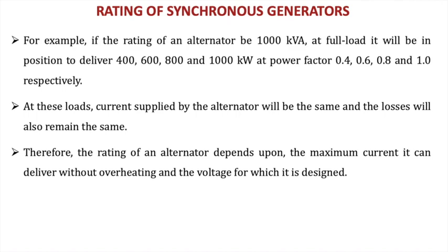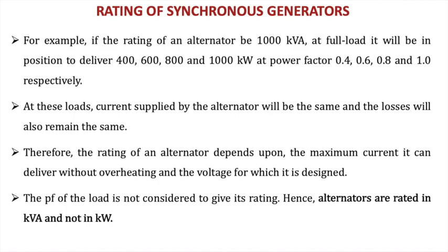Therefore, the rating of an alternator depends on the maximum current it can deliver without overheating, and the voltage for which it is designed. So the power factor of the load is not considered in giving the rating of the synchronous generators or alternators, and therefore they are rated in kVA and not in kilowatts. So this is the reason why these generators are rated in kVA. So what do you conclude? Because these generators are independent of the power factor, the generator rating is in kVA and not kilowatts.